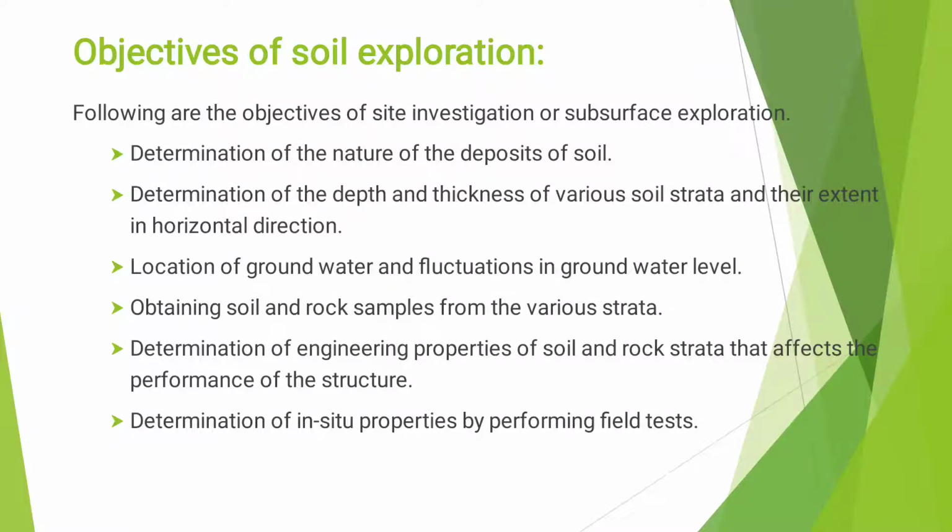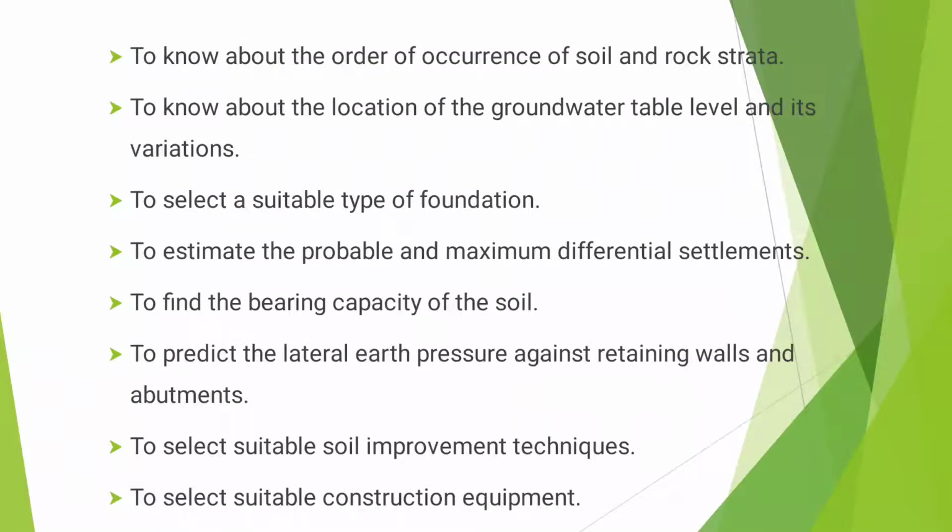The main objectives of site exploration are determining the nature of the soil deposit, determining the depth and various layers of the subsoil strata, determining the location of groundwater, determining the engineering properties of rock and soil strata, and determining the in situ properties by conducting field tests. Also, to select a suitable type of foundation, to find the bearing capacity of soil, to estimate the maximum and probable differential settlement, to select suitable soil improvement techniques, and to select suitable construction equipment.